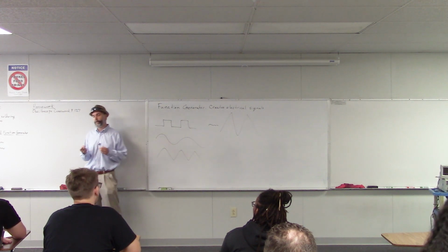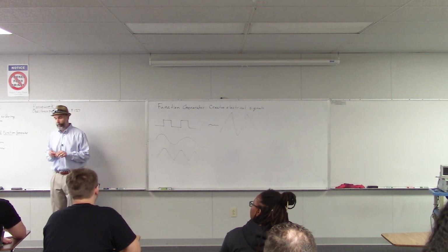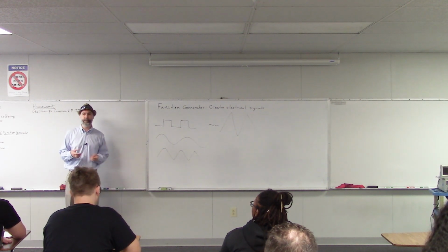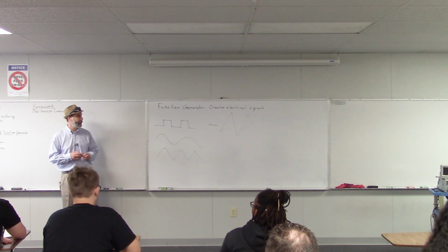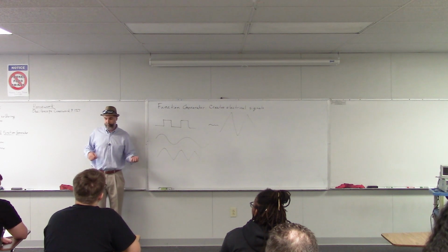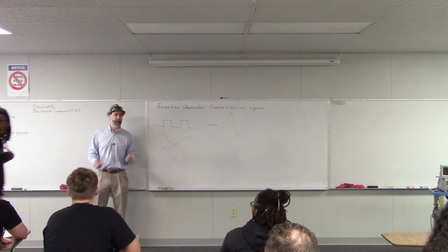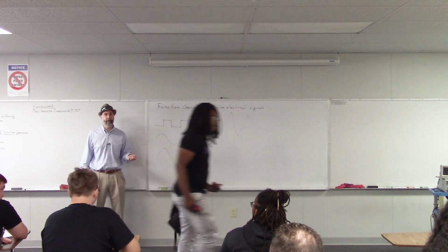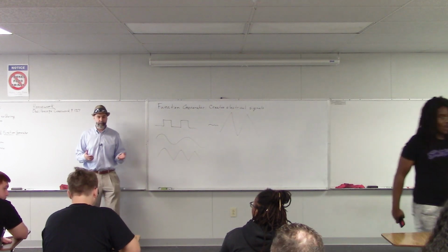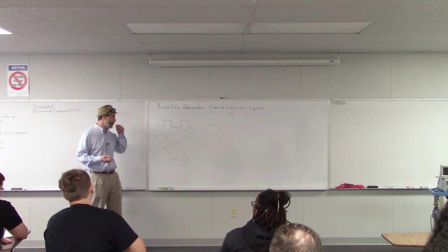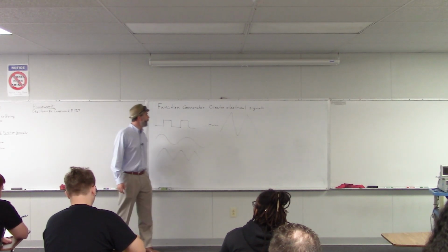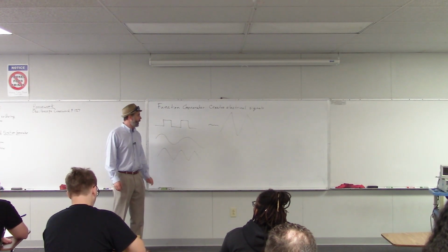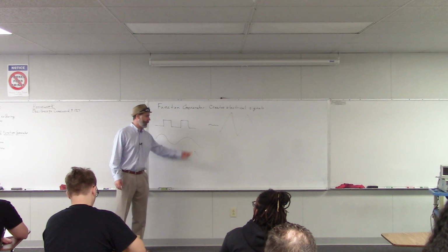So when you're testing this guitar pedal, you need the input to be super consistent. So that's what a function generator is good for. The signal that comes out of an electric guitar when you strum it is essentially a sine wave. It's a wave that looks kind of like this. Well, your function generator can create exactly that type of wave.